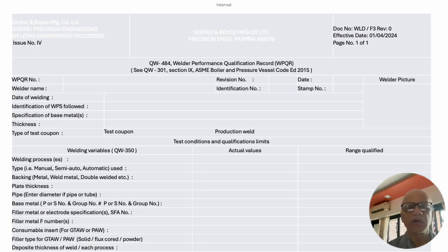It is good to refer to the production drawing so that we can see all the joints there. Most of the good fabricators identify each joint like W1, W2, or F1, F2 for fillets, or N1, N2 for nozzles, O1, O2 for overlays, whichever nomenclature you want to follow. You can mention that this WPS or PQR or WPQR is qualifying which production welds in that drawing.